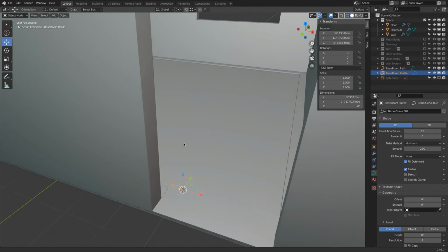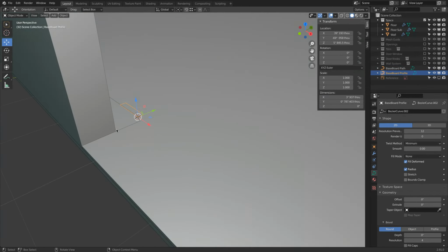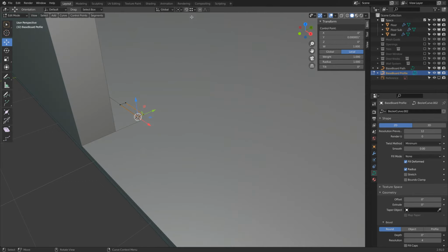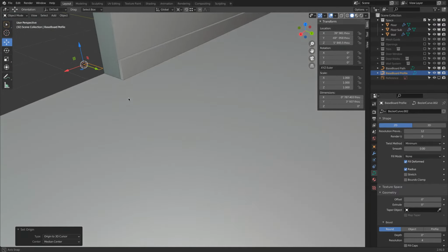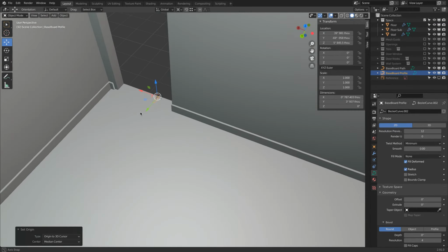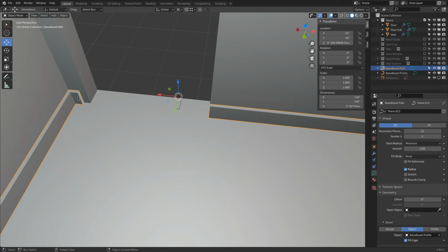That's pretty cool. Now I would like this baseboard, instead of being along the floor, to be vertical. So I have my 3D cursor there, and I can go R, Y, and Z. Okay, good, so this works. This is minus 90 degrees, but now we can see it's inside the wall. So this is actually our center point. There. Pretty nice. Okay, this one is too short.